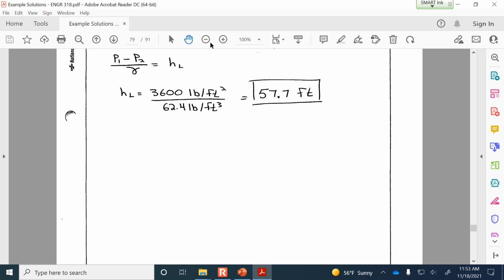Okay, now divided by 0.025 times the length of 145 feet. Okay, and all of that is to the 1/2 power. What we're looking for is the velocity should be 31.96 feet per second as the flow through the pipe. 31.96.